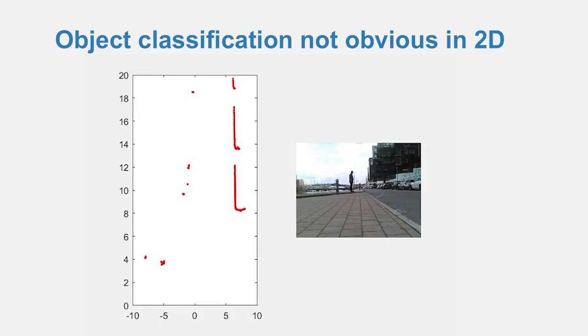Here you instead see the same sequence, but in motion. It is easy to identify the moving vehicle, and it's even possible to see the motion of the legs of the pedestrian and the bicyclist. Note the LiDAR shadows behind the objects. See, for example, how portions of the parked cars have missing LiDAR measurements as the car and the bicyclist passes. That is, the LiDAR can of course not pass through the solid objects, shadowing objects behind.